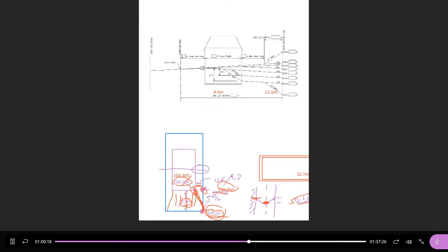So let's describe this one more time before we go on. If you know the elevation at the front and you know the elevation at the back, the difference, which is what this number represents, the difference tells you what kind of design you need to perform. So if the elevation at the back was 3 meters higher than the front, then you would design it like this. Go up at 3% to this point here, go up at 3-to-1, and then the difference between this elevation and your existing ground elevation at the back, the difference would be the height of the wall. Okay, any questions about that?